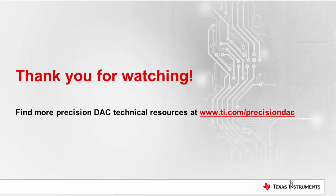In summary, we learned first about the properties of an ideal DAC. Then we looked at specifications that show where a DAC deviates from being ideal: offset and zero code error, gain error, differential nonlinearity, and integral nonlinearity. Finally, we finished with the total unadjusted error, a way to summarize all of the DC errors in a DAC.